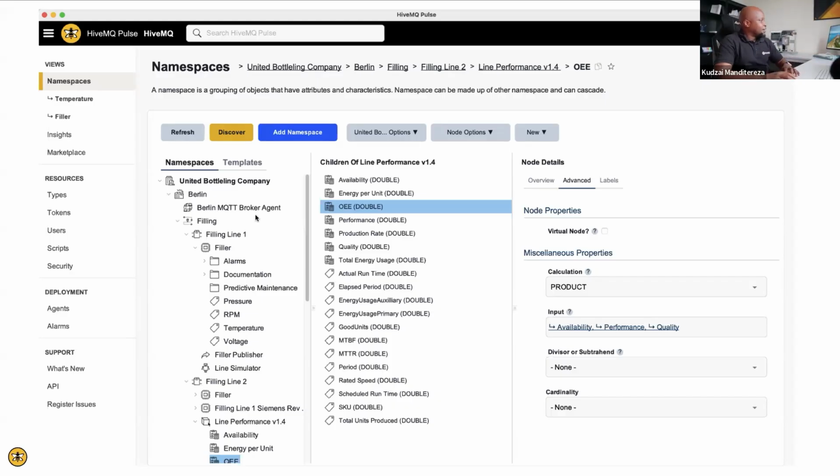And then again, you can see that here we do have a publisher node, which is a way that you can republish MQTT traffic into your unified namespace information model. You can use that specific node. So again, to reiterate, your information model is irrespective. And I saw one question in the chat asking for clarification on what it means that MQTT is not the namespace. You define your information model irrespective of MQTT, and then you could have a republisher that is monitoring your MQTT traffic and using that to hydrate your information model.